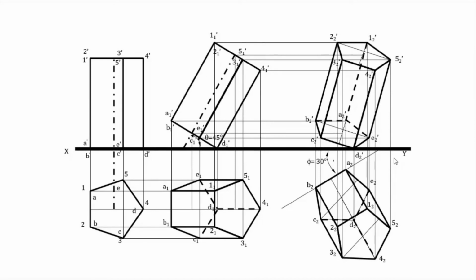Okay, so first you start the pentagon, then the front view, then rotate the front view, then the corresponding top view, then rotate the top view, then corresponding front view. So that is it. Okay, I hope you will be able to draw. And any doubts regarding this one, like dimensions or the length, angles, for the procedure, anything?